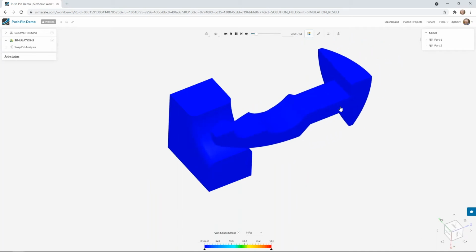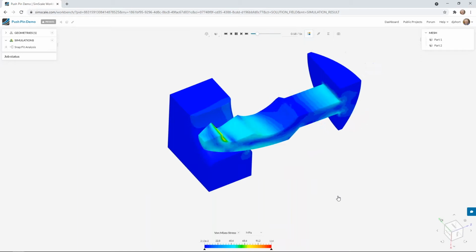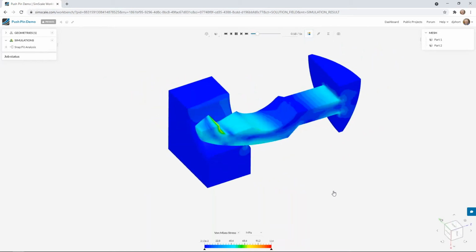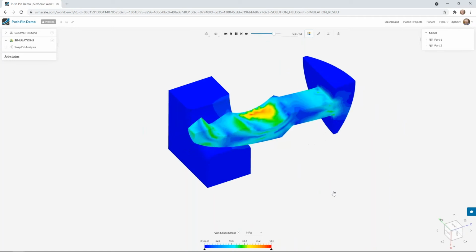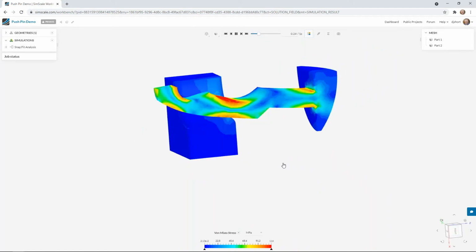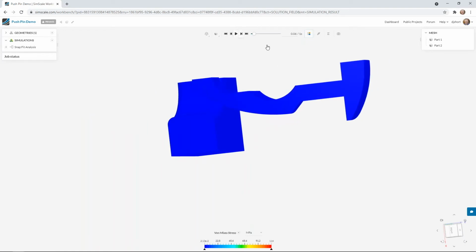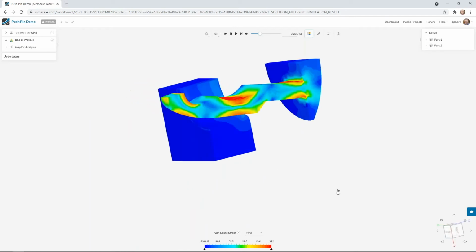Okay, so here we are in the SimScale platform. We're looking at the three-dimensional results, first of all, to understand a little more qualitatively about the deformation, the behavior, so that we can get an initial impression of what's really going on. We can pause that and we can slide it through to understand where are my areas of highest concern.